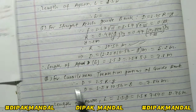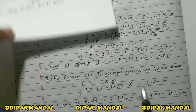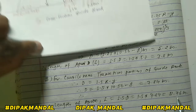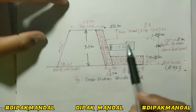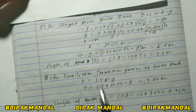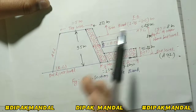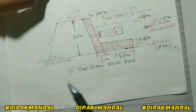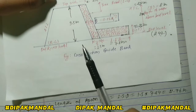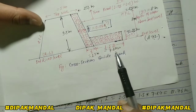Okay, now let's see the curvilinear transition portion of Guide bank. Okay, and now we have to calculate this value, that is 11.76. You have to show it in the next figure. Okay, this figure is for the straight Guide bank, and for the curvilinear transition we have to make the same figure in another. Okay, so you have to make two different figures. Okay, but for now I will show these two values in this figure.